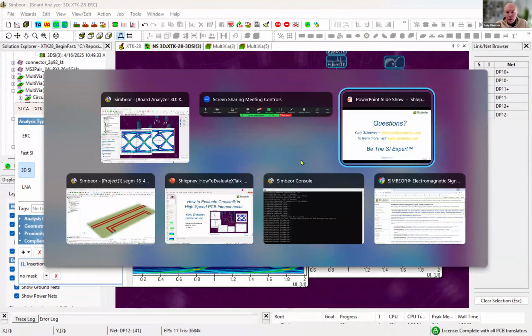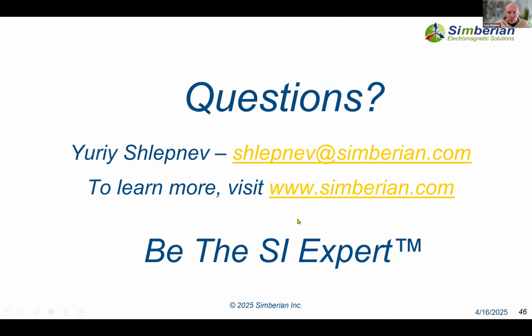And okay, we got more questions here. There are so many standards to evaluate crosstalk, such as ICN, ICR, COM. Which one is suitable for analysis in time domain, frequency domain? So ICN and ICR are based on basically frequency domain response.